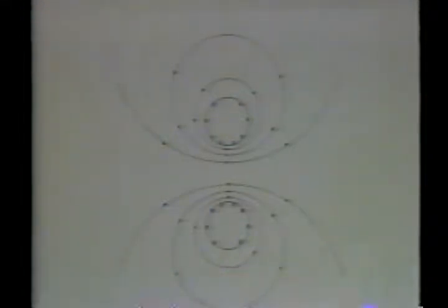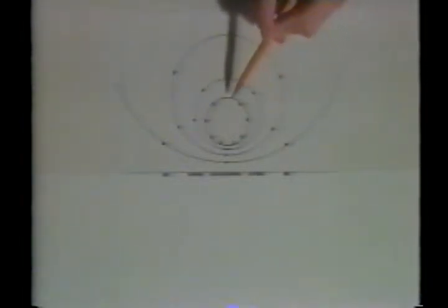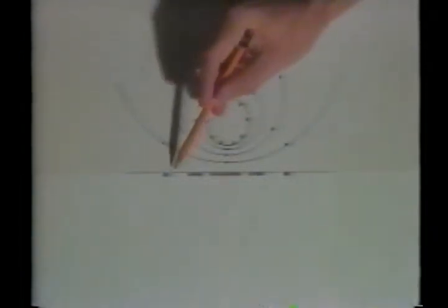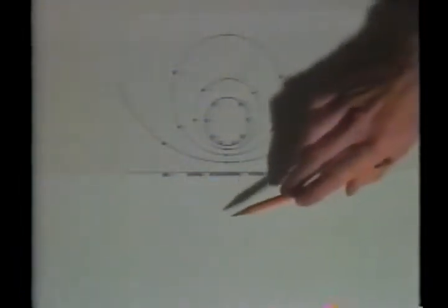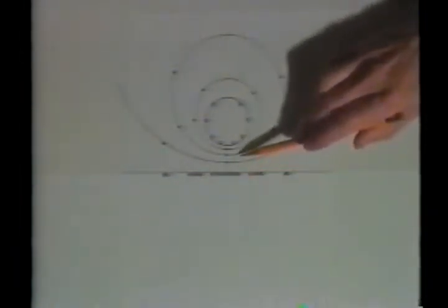When we drive a current from a 3 kilohertz source through the circular conductor, the actual currents are in the metal conductor walls, distributed in just such a way that there is no magnetic flux normal to every point on a given conductor surface. Similarly, these currents are returned in the ground plane in just such a way that there is essentially no magnetic flux density normal to the ground plane either.